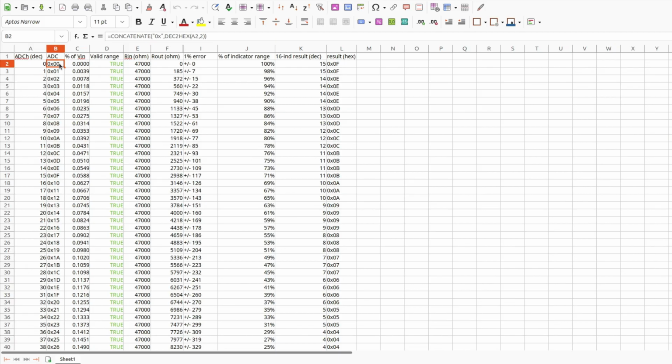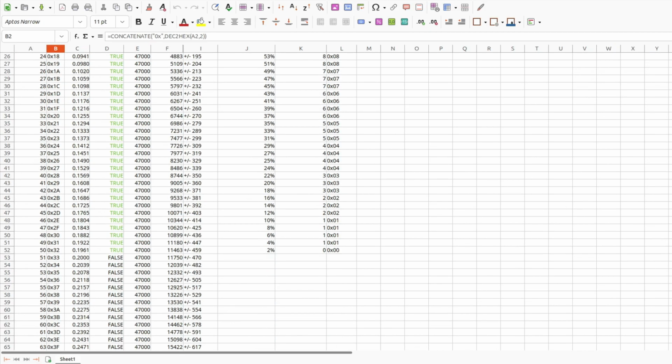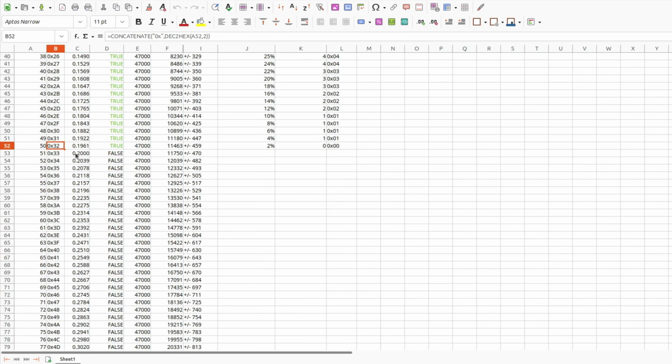So what this really means is although we have 255 possible places to identify landing zones, the ones that are really only relevant are a small portion of them, 20% of them to be exact. And that 20% must fall between the ADC output 00 and ADC output 32 in hexadecimal. So technically we could get around this limitation and open up the landing zones to the entirety of the 255 slots, but that would require some significant code changes because remember, our code still depends on the digital domain to detect the button press.